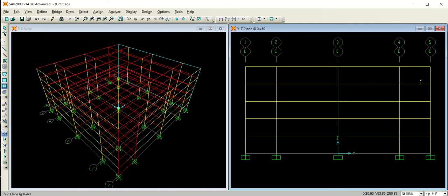You need to define the shear walls here, and then come to x equal to minus 60. Give it some time. Here you are at minus 60, draw the shear walls, right? So you are done with these steps.